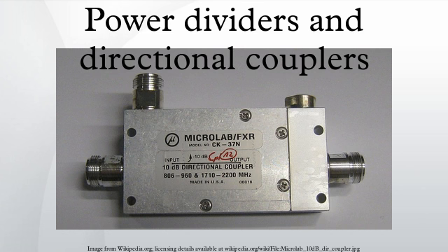The concept of a Bethe hole coupler can be extended by providing multiple holes. The holes are spaced λ/4 apart. The design of such couplers has parallels with the multiple section coupled transmission lines. Using multiple holes allows the bandwidth to be extended by designing the sections as a Butterworth, Chebyshev, or some other filter class. The hole size is chosen to give the desired coupling for each section of the filter. Design criteria are to achieve a substantially flat coupling together with high directivity over the desired band.